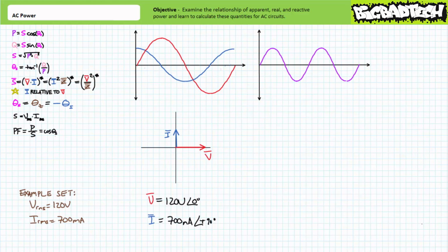Our earlier thought experiment led us to believe that given a phase shift of a full 90 degrees between current and voltage, we should anticipate a zero-centered power waveform with equal and opposite periods of positive and negative power. Given all of apparent power is now being directed towards the cyclical interchange of reactive power, we should expect none of it to be directed towards real power. Long story short, for occasions in which current leads voltage by a full 90 degrees, real power is 0, and the absolute value of reactive power equals apparent power. Let's see if this is the case.